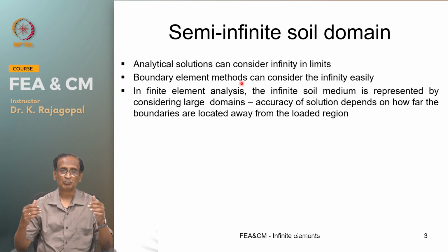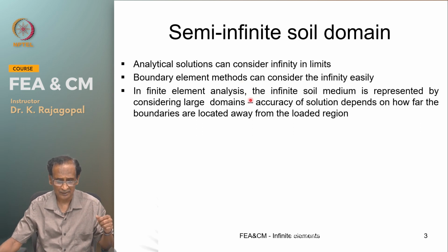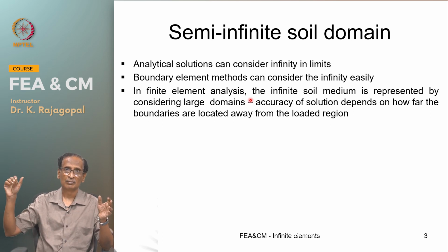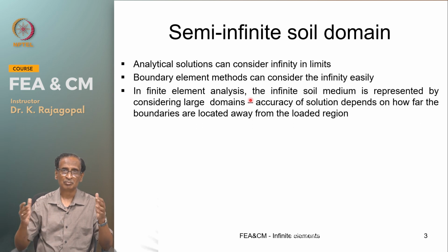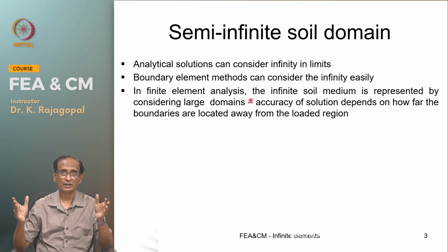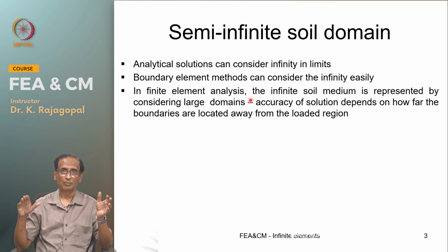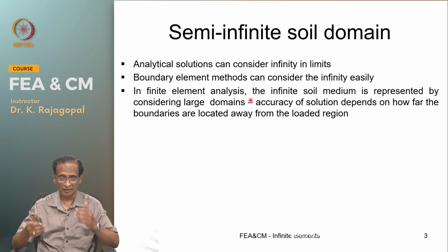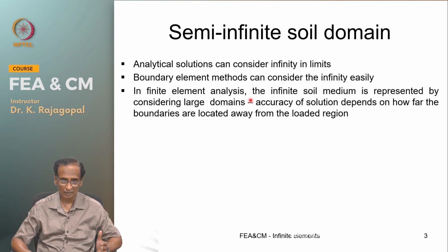Or some people consider the finite element analysis, but then prescribe some known displacements along the boundary. These could be from your theory of elasticity solutions, and by prescribing these known displacements at the boundary, we may be able to partially account for semi-infinite nature of the soil. But this may not be practicable in all the problems. Maybe in some cases we can get the solution, but we cannot do that in all the cases.